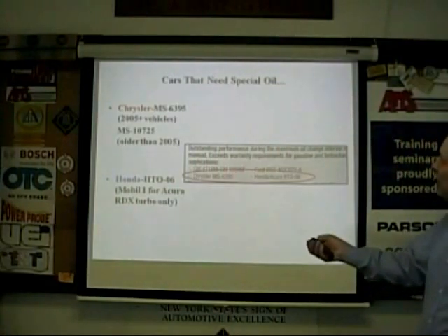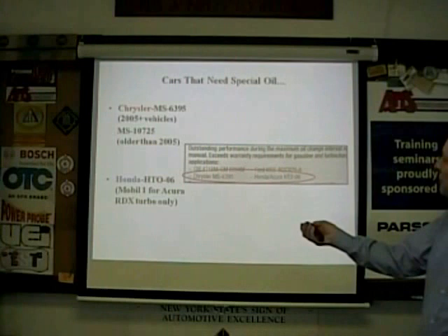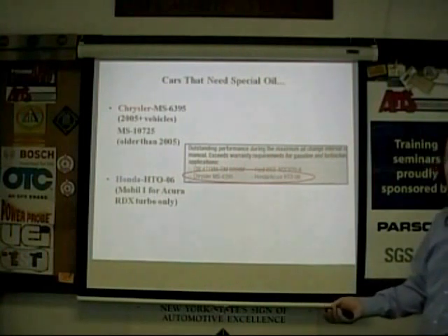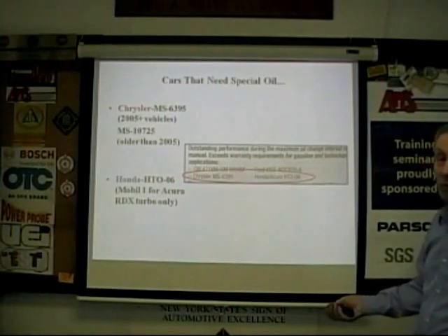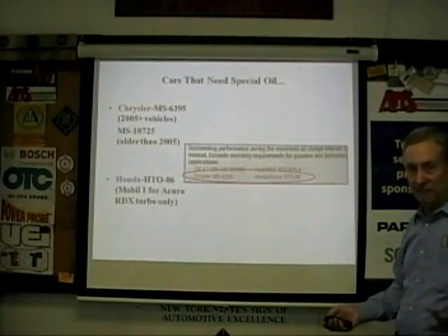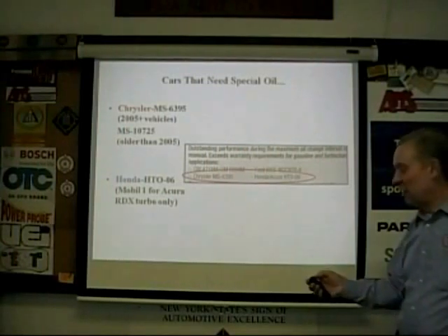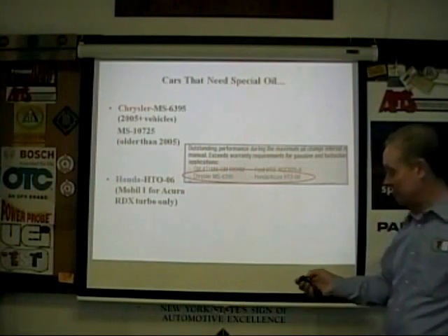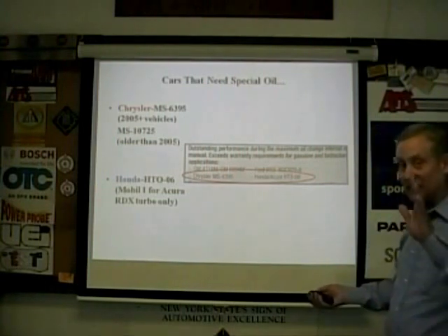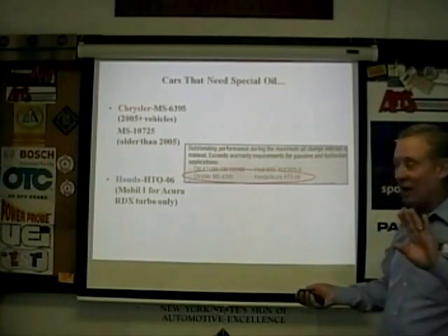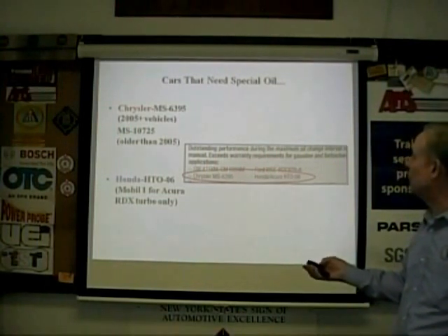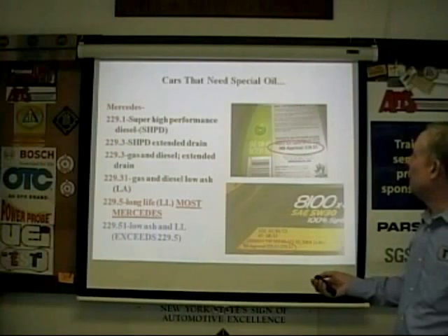All right, Chrysler. Now this one meets not only Chrysler, but it meets the Honda Acura oil. This is a Mobil 1 for Acura RDX Turbo only. By the way, on Mobil 1, I love Mobil 1. There's a lot of Mobil 1s. You have to be careful, it's not just the weight. It's the starburst, it's the spec. Long life, or, you know, high efficiency, low resistance. You got to be careful of which oil you're buying. There's a lot of Mobil 1s out there.